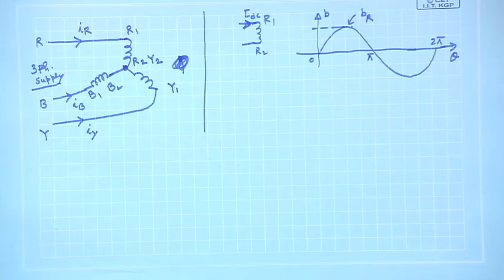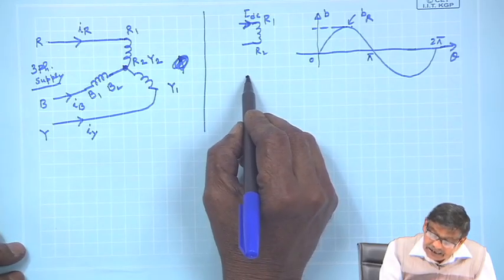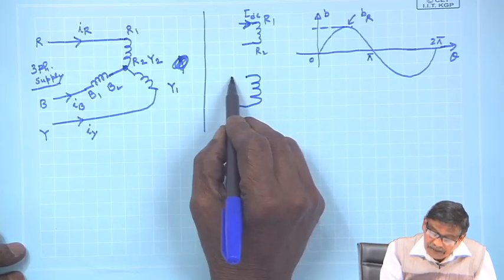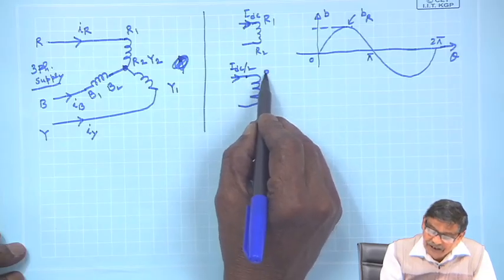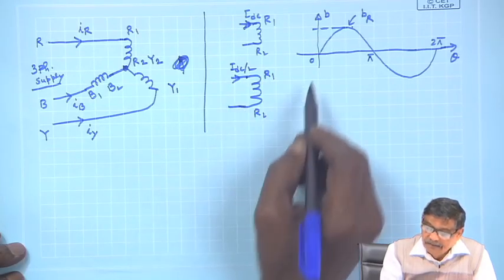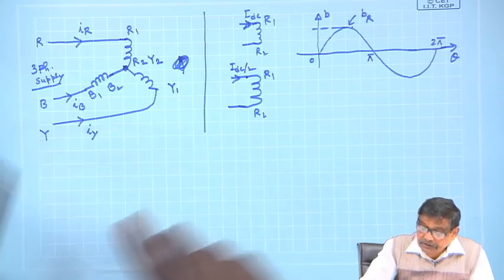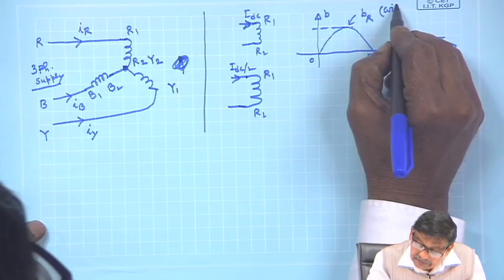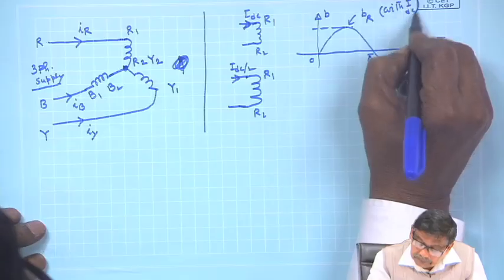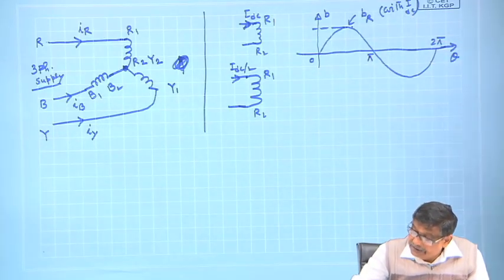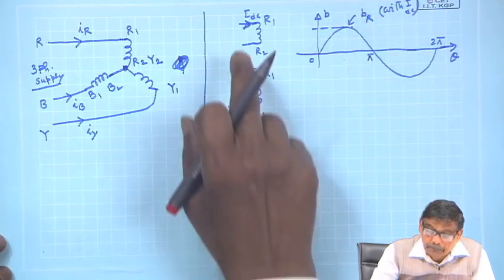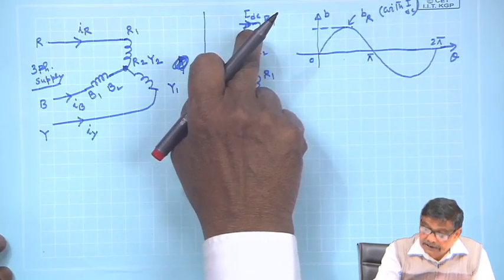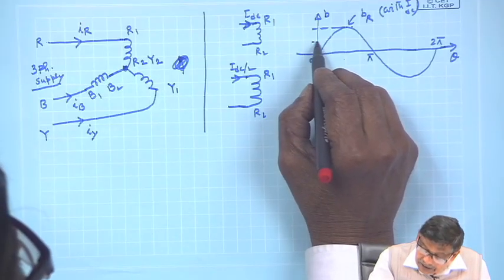What do you think if I energize the same coil with DC current, but I DC by 2, half? I have made the current half. What will be the flux density distribution? This is with I DC. If you assume linearity, the maximum value depends upon the number of turns and the magnitude of the current, so it will become half.